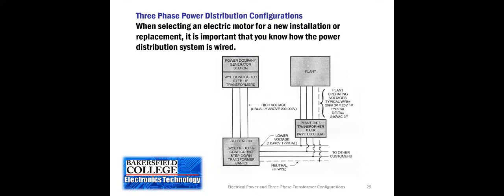So in this case, this shows if we had a Y circuit and let's say it's a small commercial building and you want to operate the air conditioners and the various other parts on 208 volt three phase, then that's great. You'll have a distribution transformer that has a Y connected secondary. Now, if you wanted to go with a delta, and instead of having 208 three phase, you had 240, then you would choose or wire a transformer that had the delta configuration for the secondary connection.